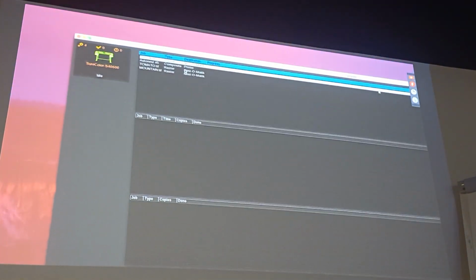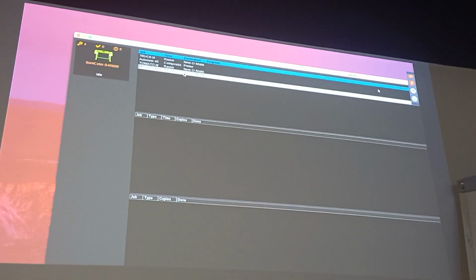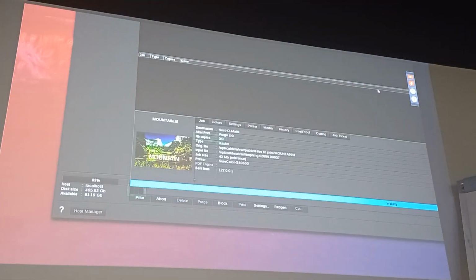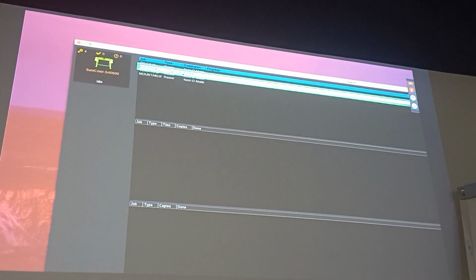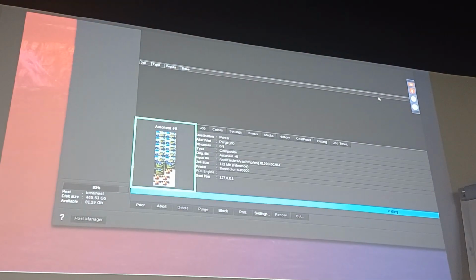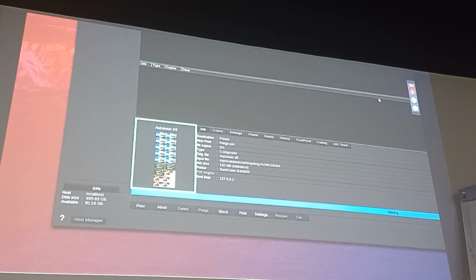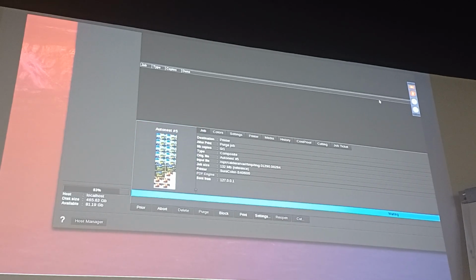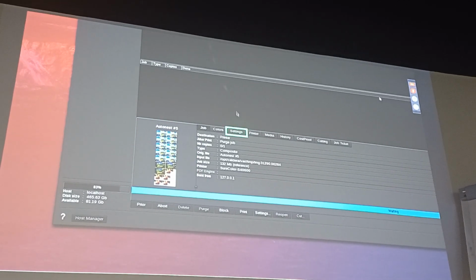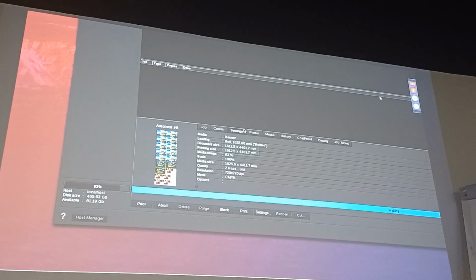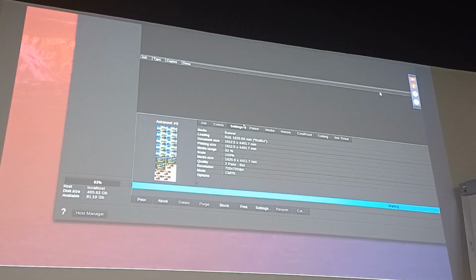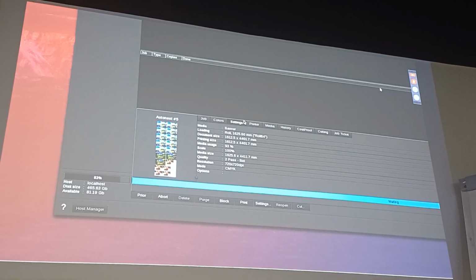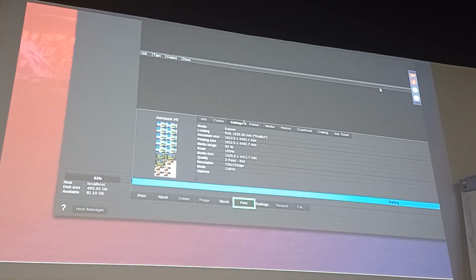In the printer queue, we can see all the files we submitted separately with the according number of copies. An AutoNest job has been created as well. As you can see in the preview, it contains all nested files as one single job. To get more information about this job, we can go in the Settings tab. Here, for instance, we can check the length of the job to not create something that is too long or too short. Let's assume we are fine with this job and we now want to print it. To do so, we will just click Print.